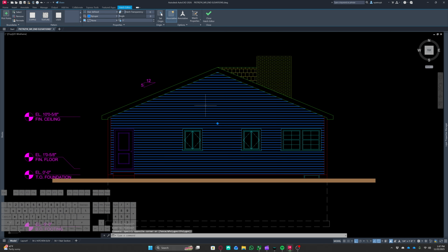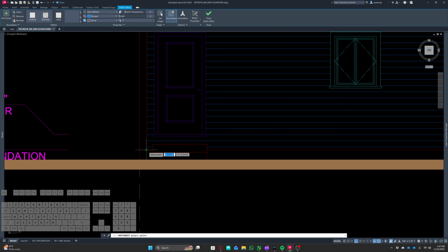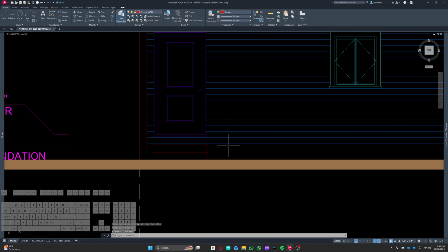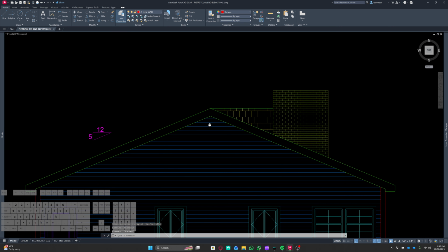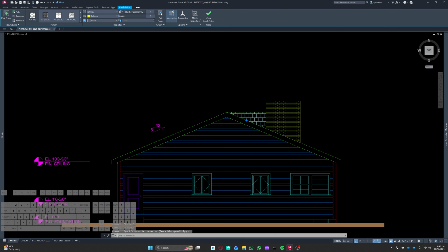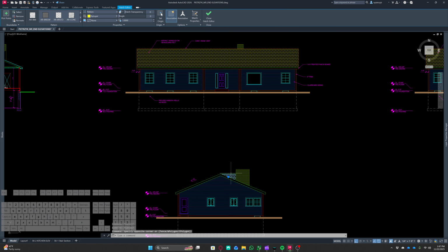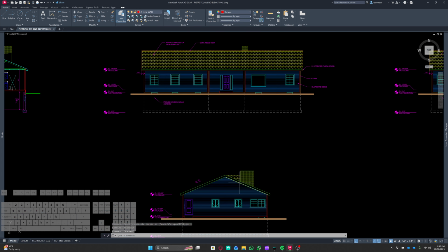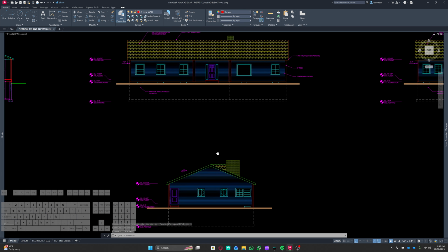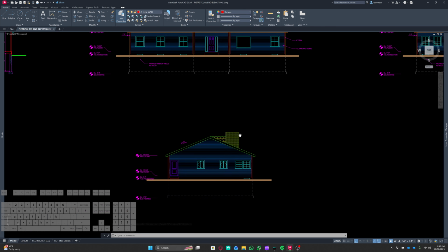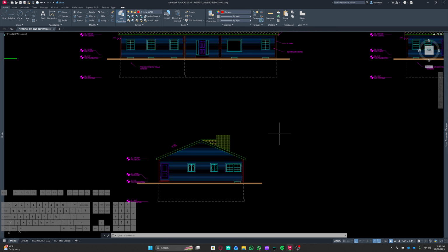Next thing I need to do is select this, and do a set origin, which is right up here. And I like to do it from the bottom left corner, because remember, you need this to be 5 inches from the bottom. Doesn't matter how high I get. The chimney's technically fine, because we don't see the bottom course, so this is accurate. So this is all good. Let's take a sip of my beverage. Good place to save.